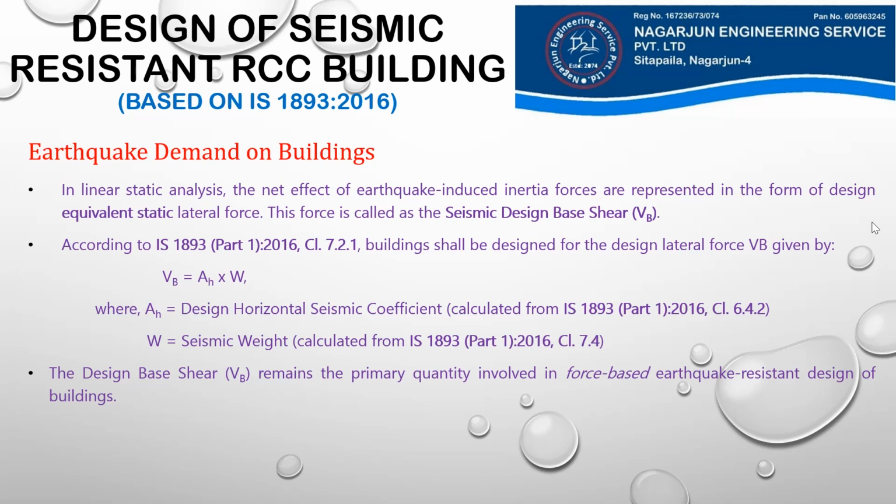That is our earthquake demand, and capacity to the building is provided by designing the various elements of the building. So let's see here, in linear static analysis, the net effect of earthquake-induced inertia forces are represented in the form of design equivalent static lateral force. This force is also known as seismic design base shear.